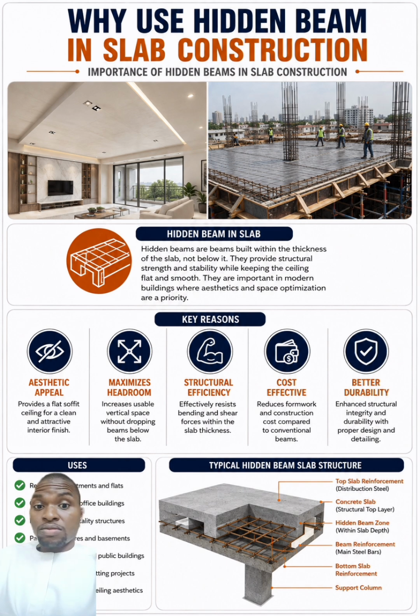So these are the reasons you use hidden beam: for aesthetic appeal, for maximizing your headroom, and for structural efficiency, considering the bending forces and the shear forces within the slab thickness.